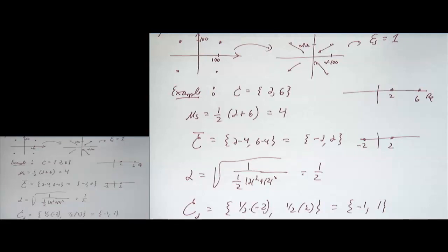With a scrambler, you essentially take a sequence of bits and you multiply it in the binary field by a pseudo-random sequence that's very long, say 100,000 bits long. Even if you have a string of all zeros, that'll make it look random and ensure effectively zero mean. So we don't need to correct for it.